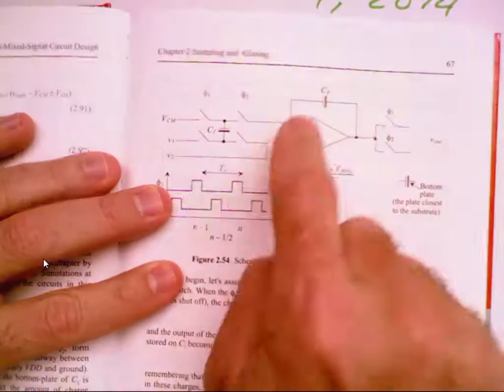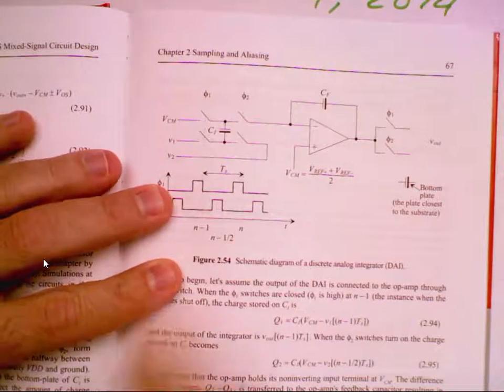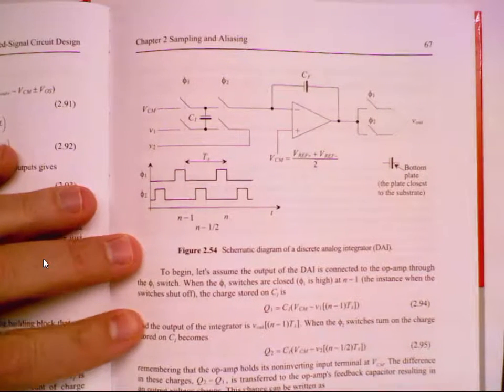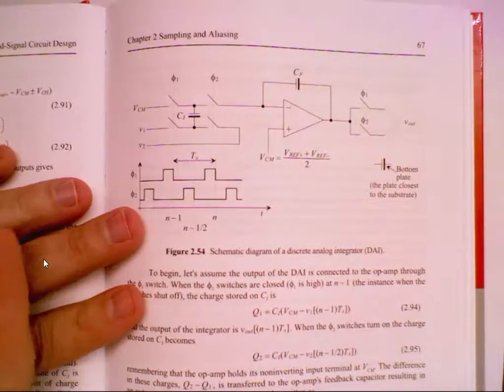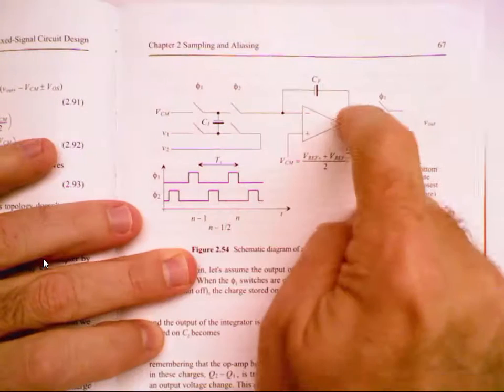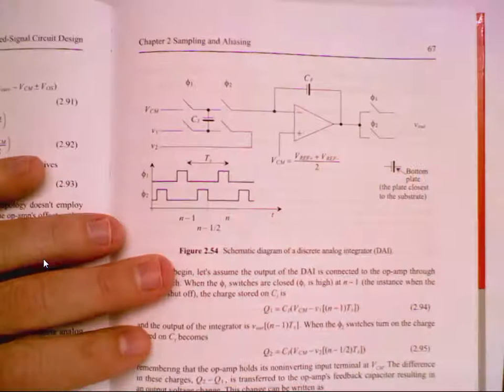Would that even work? Because you would have a circular loop. You'd have something like that. I'd have to think about that. But one thing you can do is look at the simulations and see what things are doing. You do that by putting in a DC signal and then looking at what happens on the output. You'll see this output changes, but then nothing happens until you clock phi1.